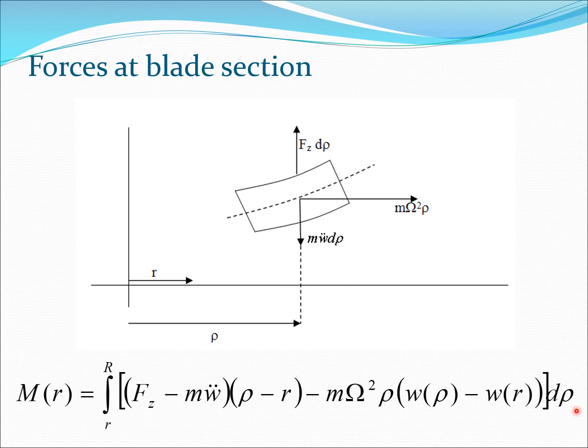Now essentially at this point we would have known Fz, we would know W, and so on. So here of course the displacement is being taken with respect to time, so that's different from with respect to space as we did previously, and so in many cases the force summation method may be better if your W double dot is quite accurate.